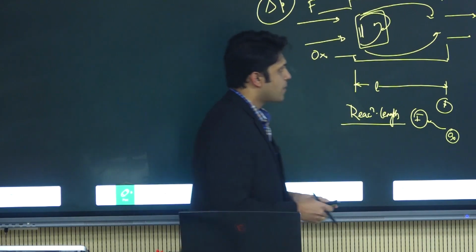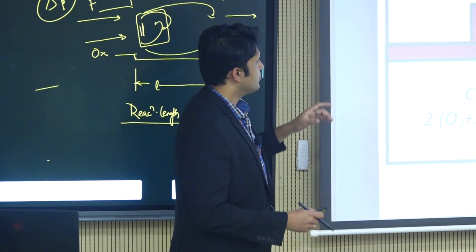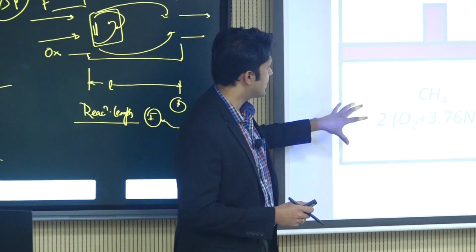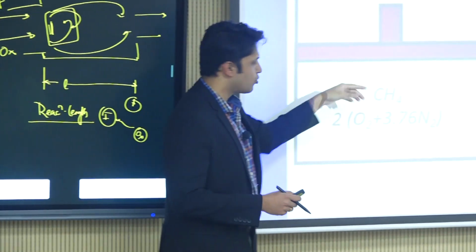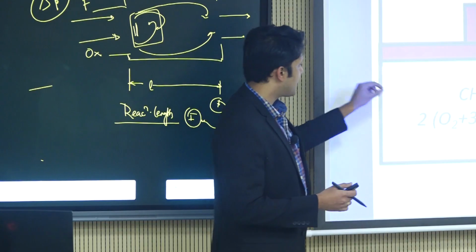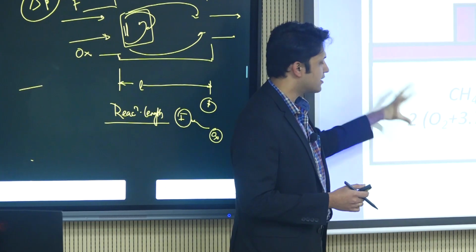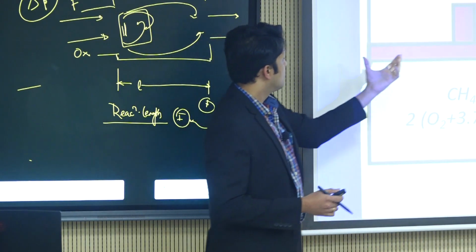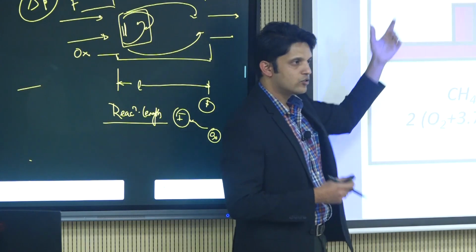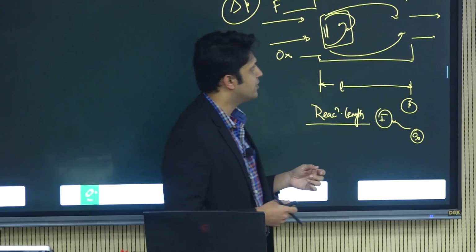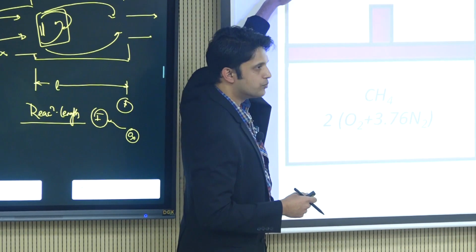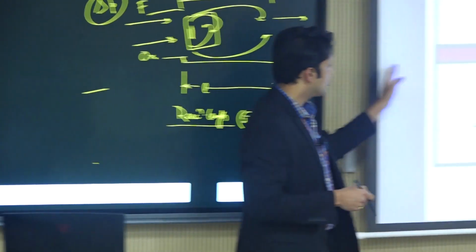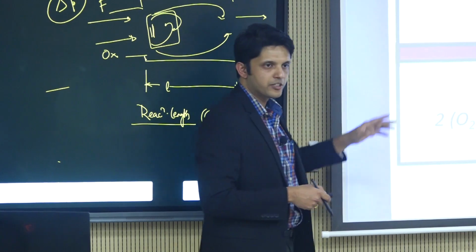So what we want to do is, let's assume it to be a constant pressure system. You have some methane and air mixture sitting inside a volume, homogeneously mixed, it is flammable, and you supply the required ignition energy to it. So it starts combusting. Once it starts to combust, what is going to happen? If it is a constant pressure system, this piston is going to expand. So the volume expands as the combustion happens, right? So it goes from state 1 to state 2. Now, if we want to calculate adiabatic flame temperatures, we are assuming that there is no heat loss through the walls or through the piston.